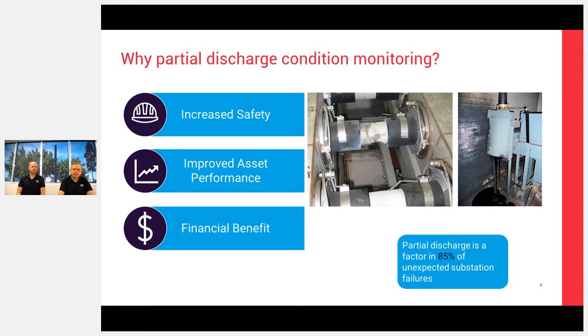Where do we get failures? Well, we get failures on new style switchgear. We get failures on old type switchgear as well. Age is not the 100%. It's not just an age-based factor. If we see the two pictures here of problems that we found, we've got the internal arc rated bus bar that has some surface tracking that's caused us a failure in that bus. Now hopefully with the internal arc rated nature of that switchgear, we've got a lesser safety impact than that, but we're still going to get the unexpected outage that's going to cause us network problems.